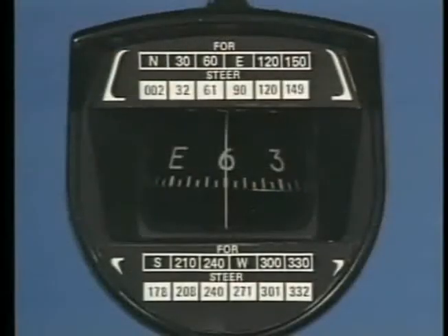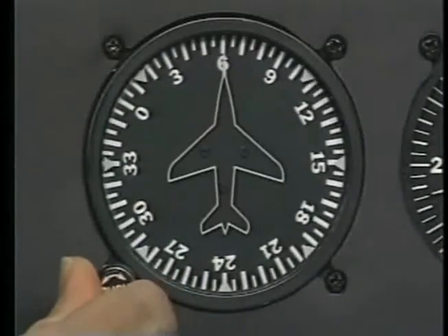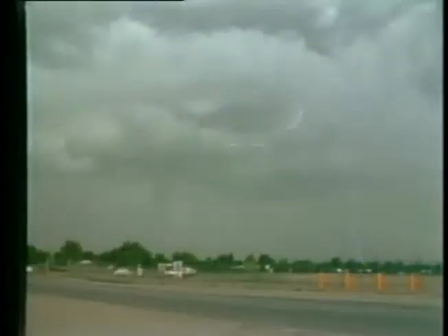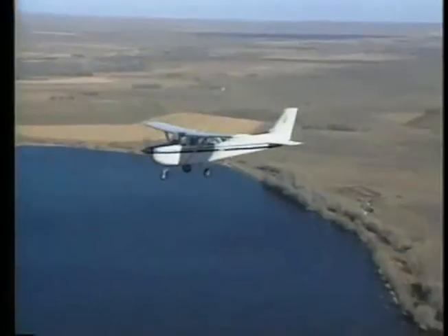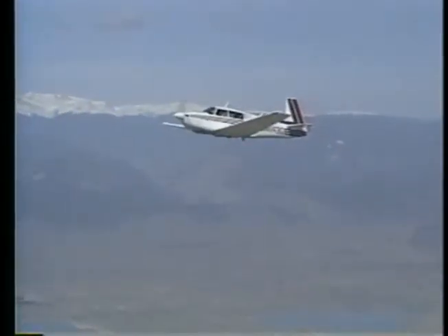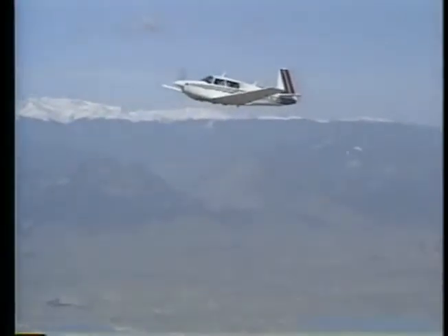If your heading indicator is not properly set to the magnetic compass, you may have problems with tracking and intercepting procedures. You should monitor these instruments often to ensure that the heading indicator has not precessed. Other phenomena that may cause erroneous readings in your ADF are twilight effect, thunderstorm effect, precipitation static, shoreline effect, and terrain effect. You'll learn more about these when you read your private pilot manual and study the operator's handbook for your ADF.